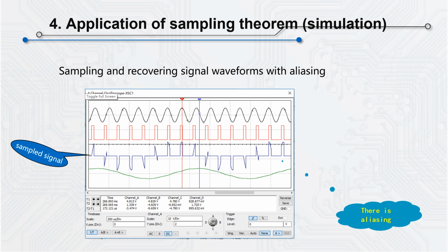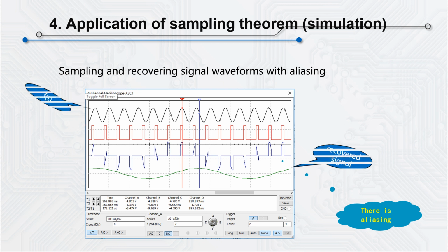For this sampled signal, when it is recovered by low-pass filter, we can get such a green curve. As you can see here, there is a change between the green curve and the original f(t). It is widened, and there are certain small high-frequency glitches on the curve. In fact, this is a kind of sampling with aliasing.